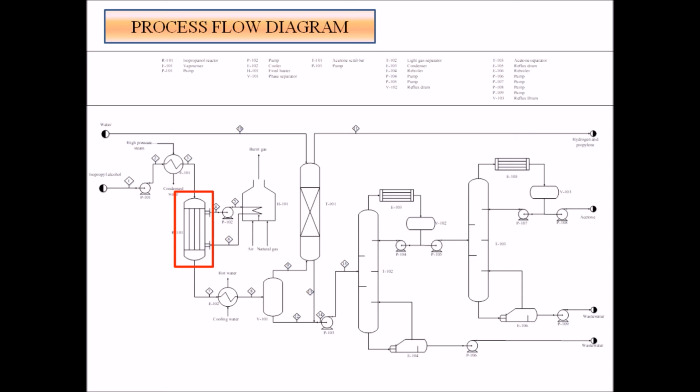The plug flow reactor is the most suitable reactor because it is suitable for large-scale, fast, and continuous reactions at high temperatures. It offers high conversion per unit volume, low operating labor costs, and efficient heat transfer. The operating pressure of the reactor is 2 bars and the operating temperature of the reactor is 350 degrees Celsius. The conversion at this temperature and pressure is 87.8%. The reactor exit pressure is 1.9 bars. The reaction is endothermic with heat being supplied by the circulating stream of hot molten salt.